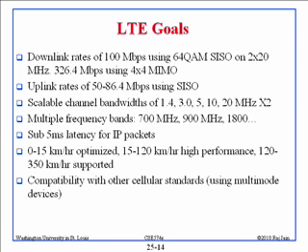So that is not adaptively changed in any of the technologies so far, because that is one of the fundamental parameters. Just like we don't adaptively change the intercarrier spacing. So for example, in WiMAX the intercarrier spacing is 10 kilohertz. In LTE it is 15 kilohertz. That is not changed. Basically we keep that fixed universally. So whether you use 1.4, 3 megahertz or whatever channel, this intercarrier spacing is 15 kilohertz fixed. Right? Similarly, the cyclic prefix is fixed.